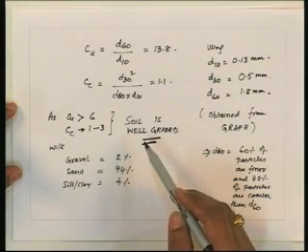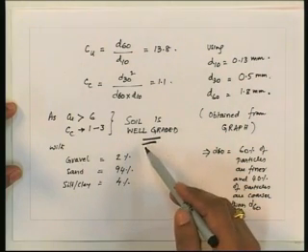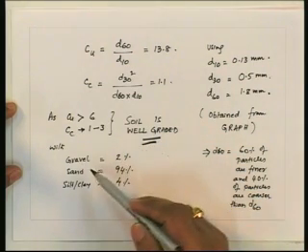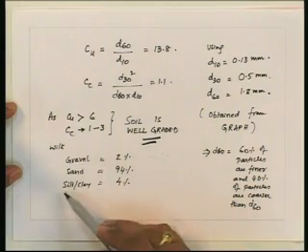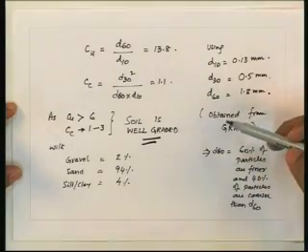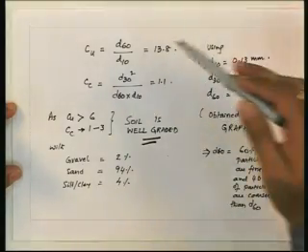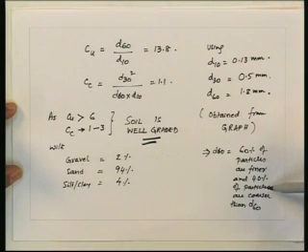Once we complete this analysis, we say that the soil is well graded with percentage gravel 2%, percentage sand 94%, percentage silt clay 4%. To revise once again, D60 is nothing but the size for which 60% of the particles are finer and 40% of the particles are coarser than D60.